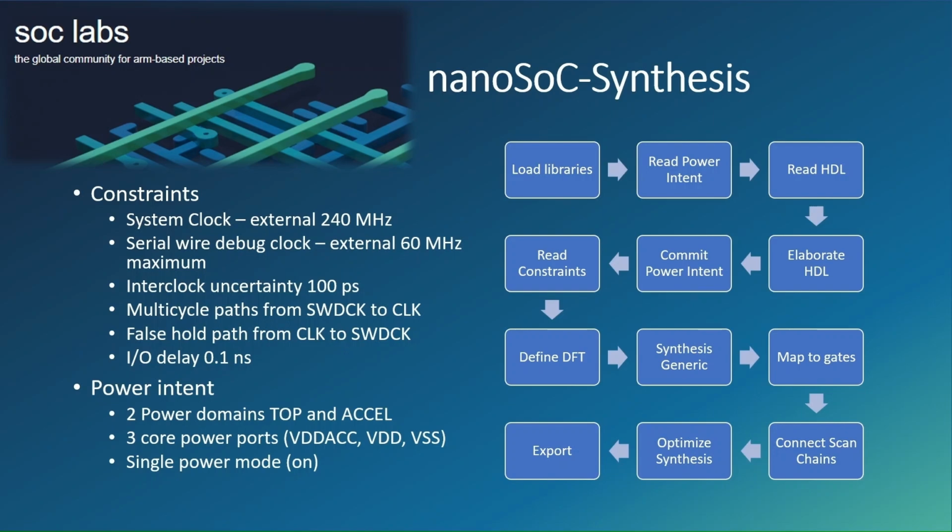And as John was saying before, one of the big points in academia is power measurement. What we've done there is split NanoSoC into 2 power domains. So we've got a top level, which has the M0, the DMAs, and the memories, and then an accelerator power domain, which is purely the accelerator. What we've done with that so far is taken it to the pin level. So there's an accelerator power supply separate, so that we can measure externally.